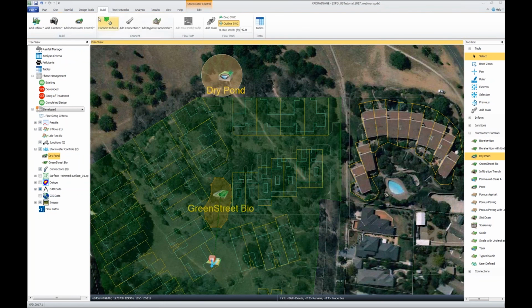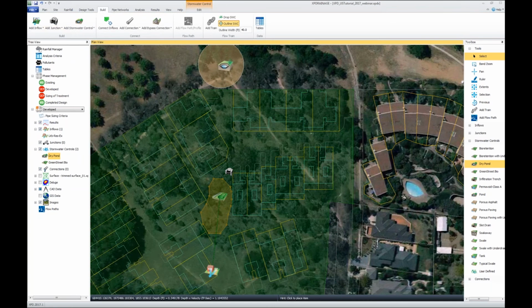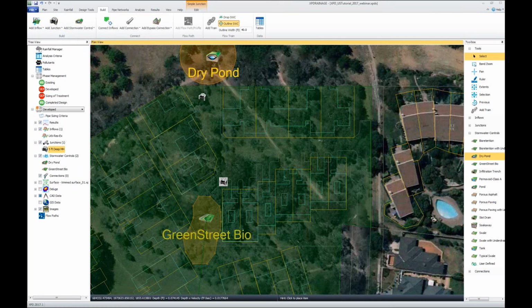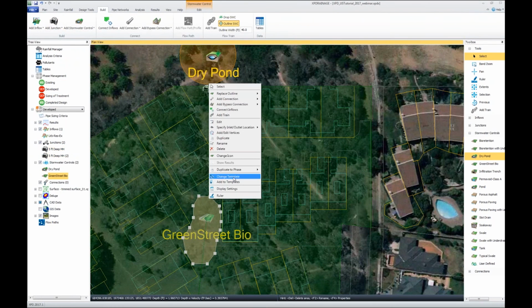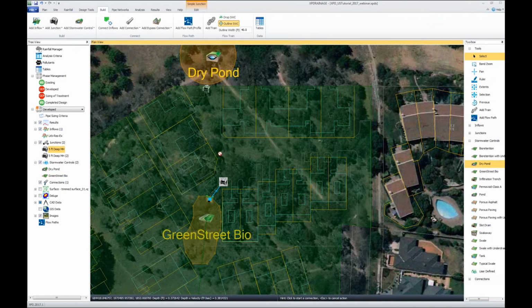I can add in items. Again, I'm not going to spend a lot of time moving through this world here in XPDRAINAGE. I want to show a lot more how it integrates outside the software, but I will at least set up. You'll see how long it takes to set up a system. I can add in some manholes, and I'll manually connect the system. So these are pipes. I have a pipe leaving my rain garden, goes through these manhole inlets, and daylights out into my pond.